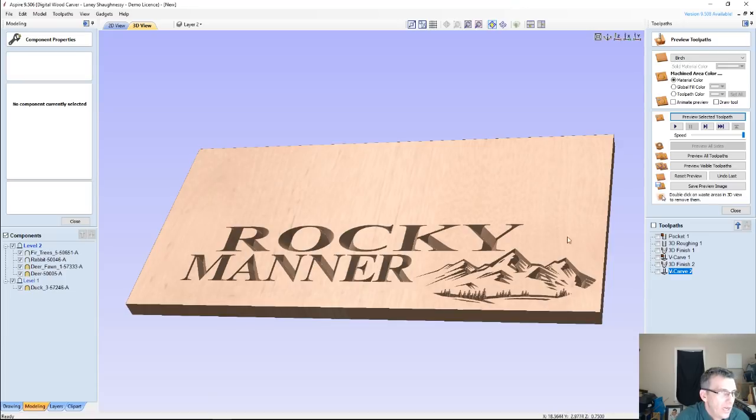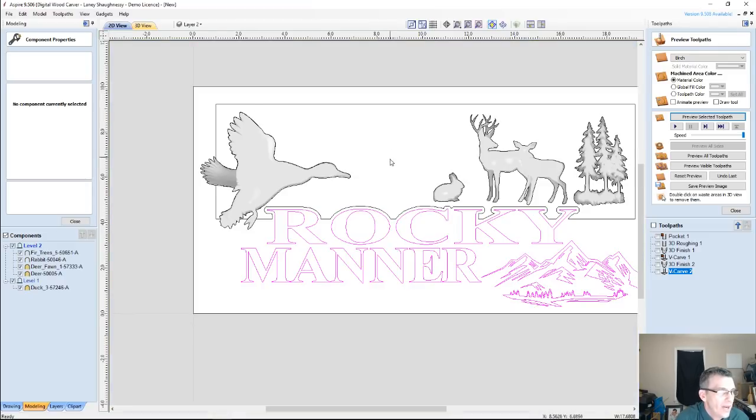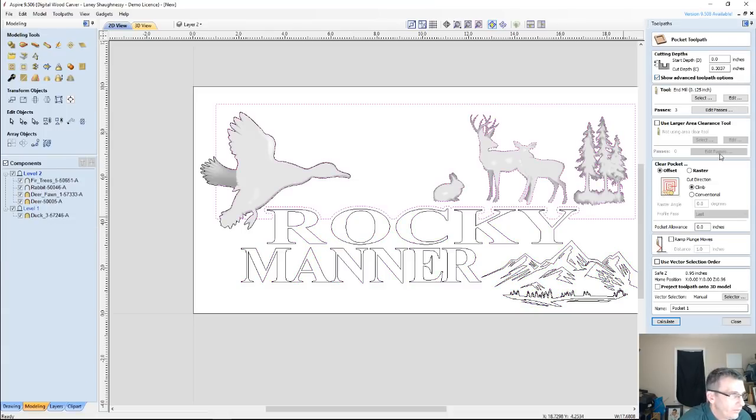Okay? I'm creating a pocket. I'm physically creating a pocket in my job, and I want that pocket to be as deep as the bottom of the models. In order to achieve that, I have to do some math. I have to take 0.75, the top of my board, subtract my model thickness, and the little gap of wood I have above the model that I'm milling away, that's waste wood, in order to obtain that magic number, 0.3037, 3038, one versus the other. Okay?